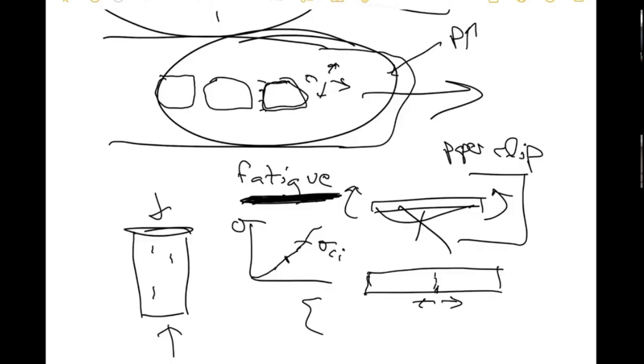But notice, when I push it this way, you get a crack, but that crack is not getting stretched as much. It's getting stretched a little. When I push it, it generates tension, but then the crack forms and the tension goes away. That means now the load goes to that, and now this guy cracks and the tension goes away, and then this guy, and they go all over the place, and they're stable.